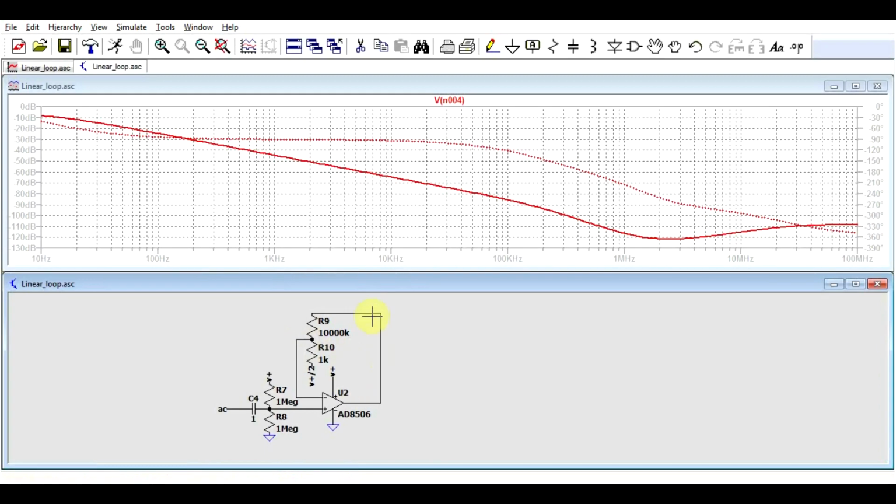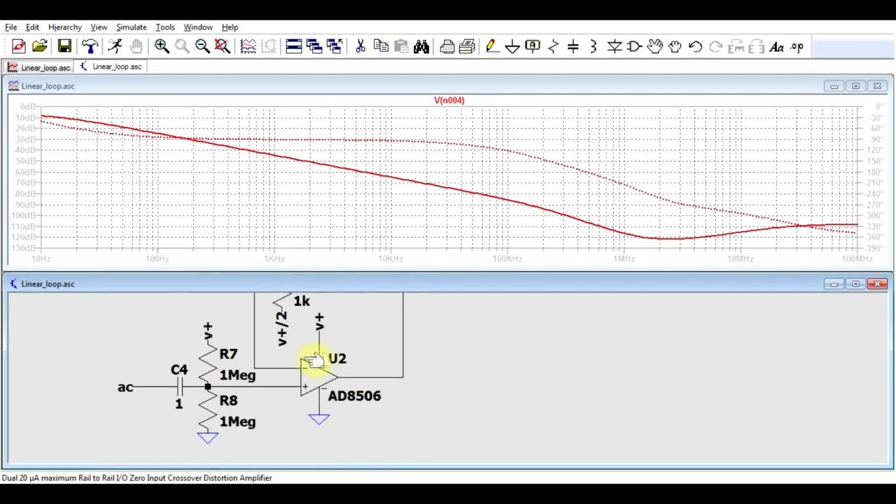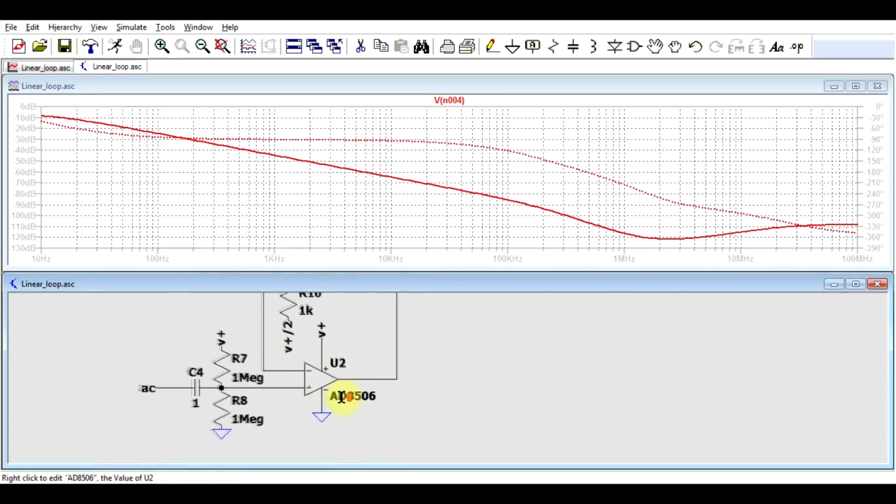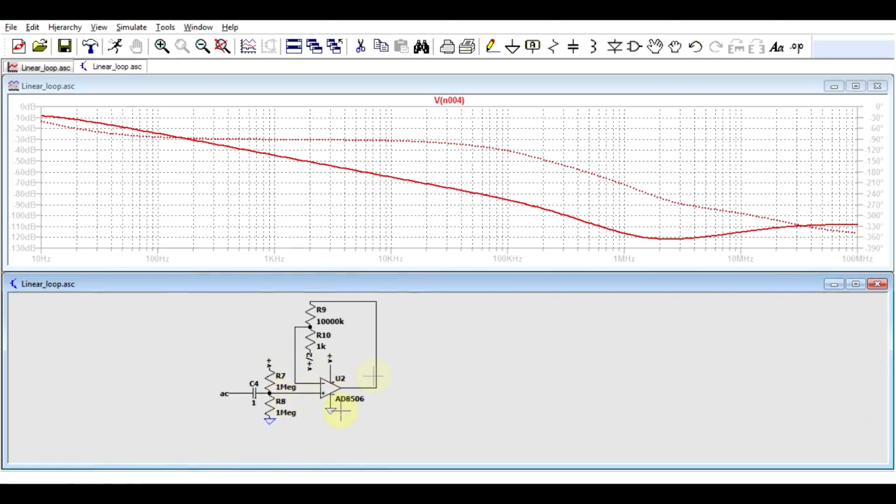That is because this circuit will not work in a normal transient type of simulation. Why is that? Well, we're trying to amplify by a factor of 10,000, and we should be able to do this, but we've failed to take into account that this op-amp has a bit of offset voltage. So whatever offset it has, we've amplified it by 10,000, and it probably ended up saturating the output. So it either gave us a saturated positive output or a saturated negative output.